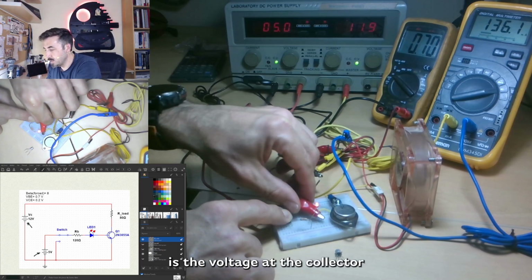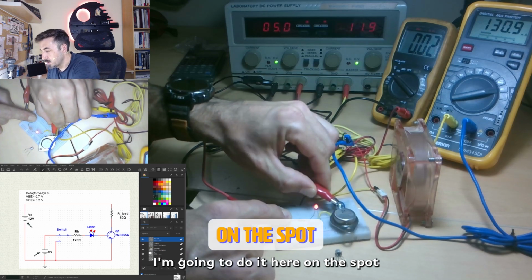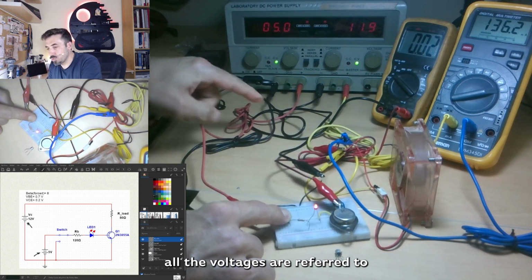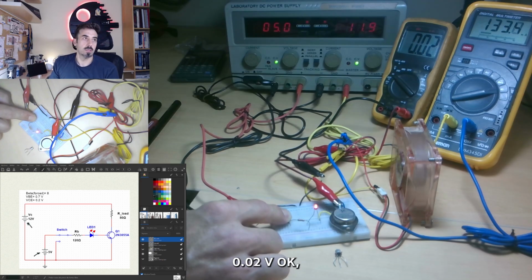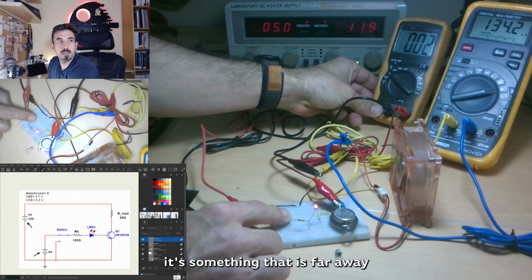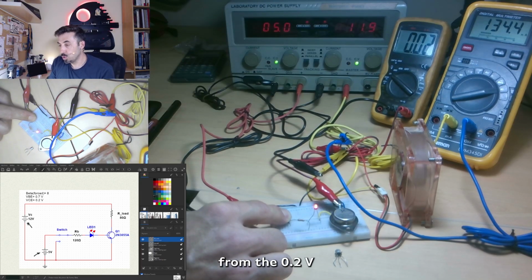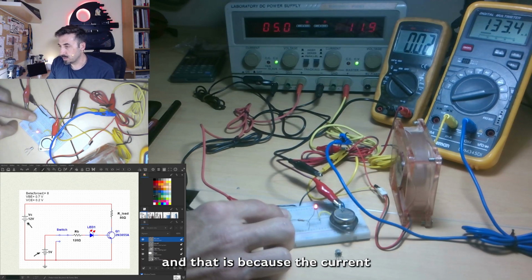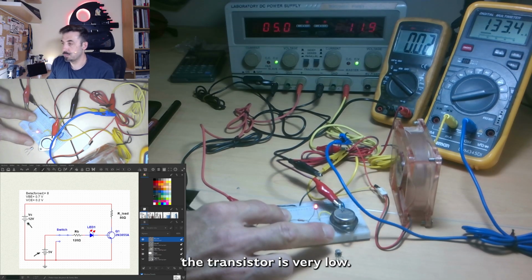Another interesting thing is the voltage at the collector. I'm going to do it here on the spot. All the voltages are referred to ground. Ground is common for both voltage supplies, and look here, it's 0.02 volt. It's something far away from the 0.2 volt, and that is because the current passing through the transistor right now is very low.